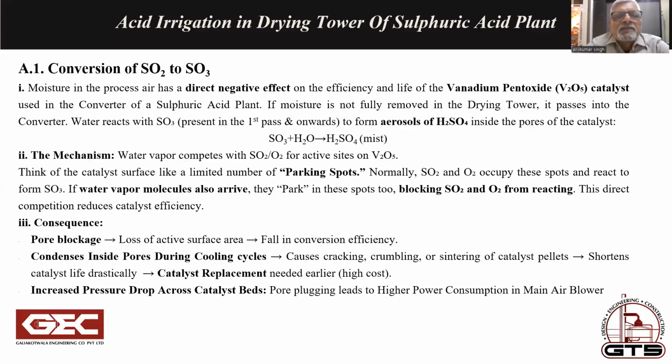Water reacts with SO3 present in the first pass up and onwards to form aerosols of H2SO4 inside the pores of the catalyst. H2O plus SO3 gives H2SO4 mist. In the mechanism, water vapor competes with SO2 and O2 for active sites on V2O5.